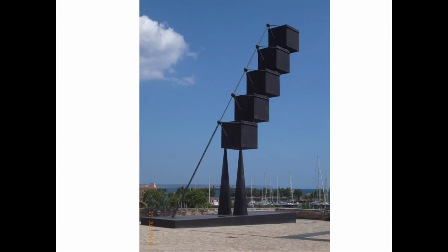It's only a sculpture. It's that kind of, engineers call it, I think, something like structural gymnastics. But actually, if we look at it carefully and understand how it's working as a cantilever and what's in pure compression and what's in pure tension, we can see exactly what's going on. The load path is that these boxes, which are hollow, obviously not that heavy, although made to look heavy, all the loads are travelling down here and back to, again, look, elegant, tiny little points of connection, triangulated for stability, the main columns.